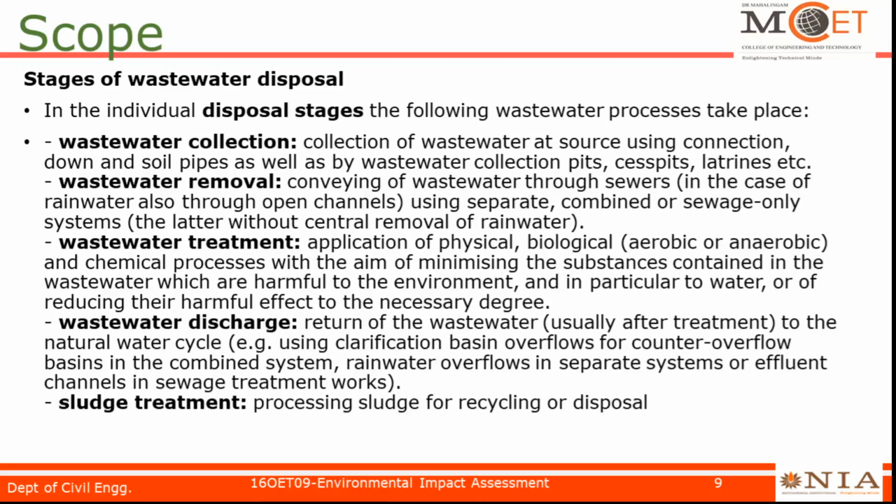Wastewater discharge: return the wastewater to the natural water cycle, using clarification basins, overflows or counter overflow basins in the combined system, rainfall overflows in separate systems, or effluent channels in sewage treatment works. That is, we are discharging the wastewater properly after treatment. So what they do is bring it back into the water cycle, right?